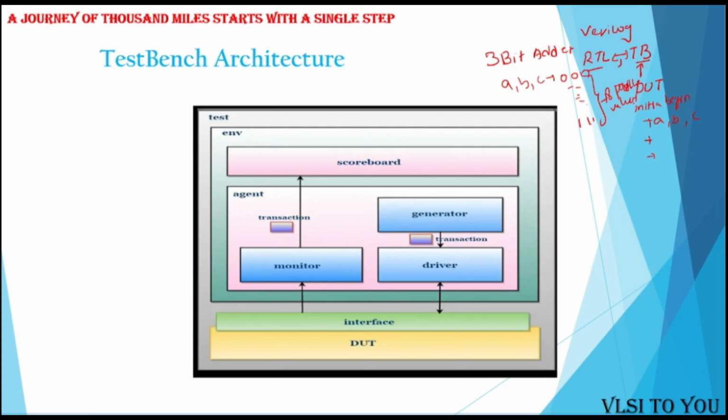All these values enter into the RTL and it works on them. After the logic has worked, you will write the $monitor system task in the testbench. This monitor will be monitoring all the output values coming from the RTL.